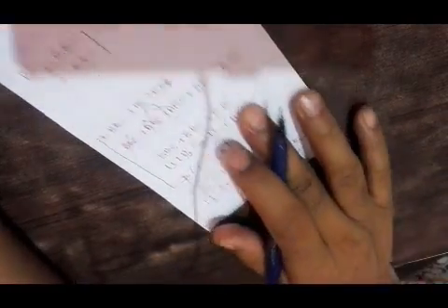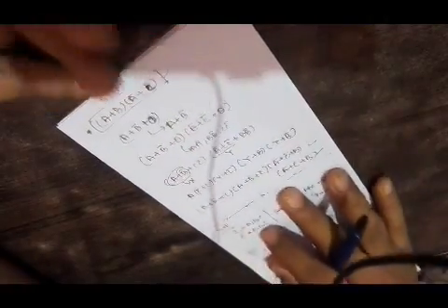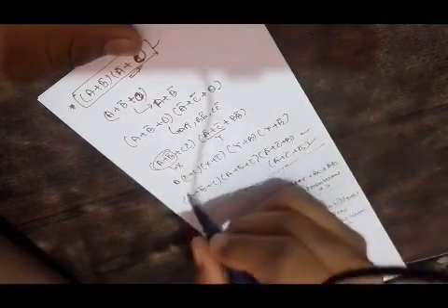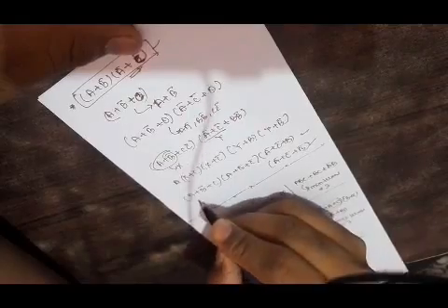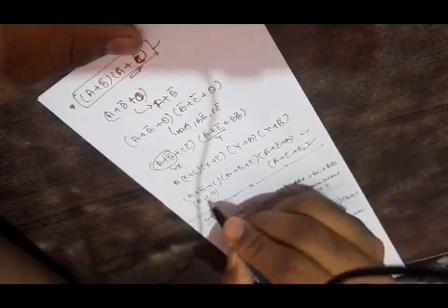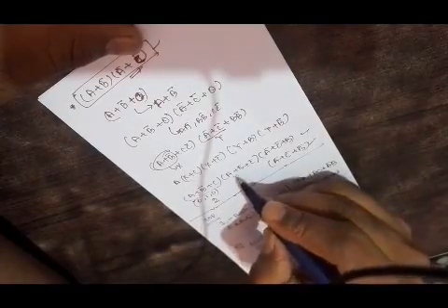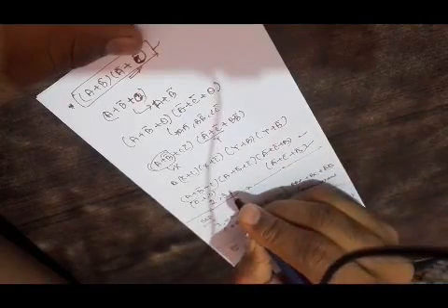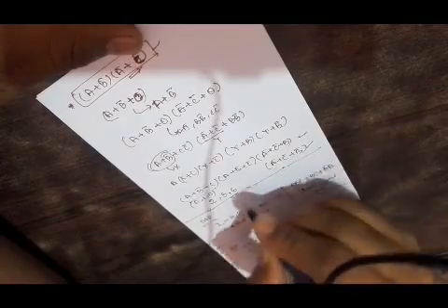Similarly, you can also convert this A bar, B bar, A plus B bar into A plus C, this one, into its canonical form. We have expanded into the canonical form, and we can then write this as 0 1 0, and this term is 2. So it is 0 1 1, it's again 3. It's 1 1 0, that means it is 6, right? And it is 1 1 1, it's 7.